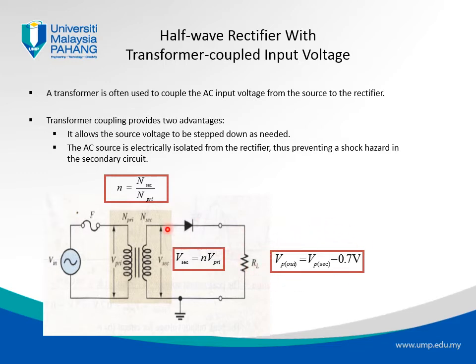So in terms of calculation, the VP out is still the same, right? The voltage at the output of the rectifier, of course, the maximum voltage, the peak voltage of the half wave of the output of the rectifier, is still the same. It equals V maximum or VP minus the bias, which is 0.7 volts.